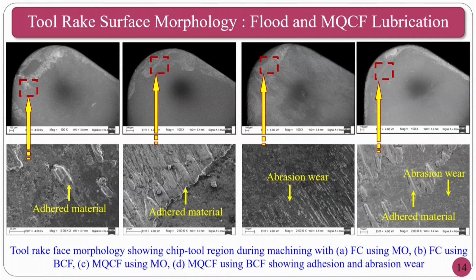For that purpose, flood cooling and minimum quantity cutting fluid, that is, minimum quantity lubrication, were tested at our laboratory. The secondary electron image is taken here, where you can see the sticking region on the material also. This is flood cooling, and this is MQCF with mineral oil. Normally we also tested some advanced cutting fluids, called bio-cutting fluids, with both flood cooling and MQCF.